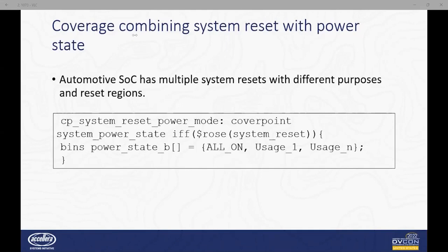Automotive SoC will have multiple system resets and segmented reset regions, and the operation of the power mode state can be different for each reset event. So it is important to verify that the reset assertion and deassertion behavior in all possible power mode states is working as expected.